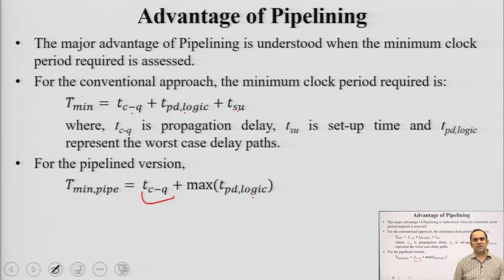Among these 3 combinational logic blocks, the block which has the maximum delay, you only take the value of that block, because by the time that much delay occurs, the other 2 would have already calculated their outputs. Okay. So, you only take the worst case scenario, only the maximum. This is sort of a parallel version of a series operation.